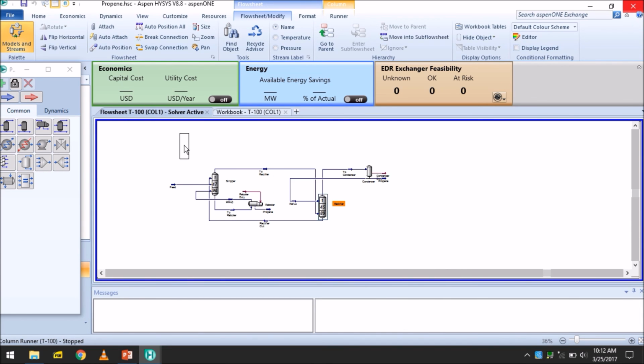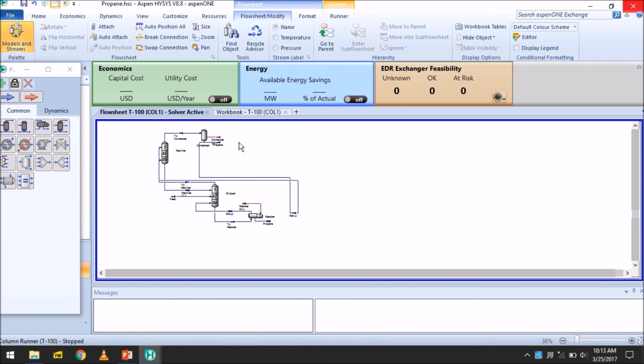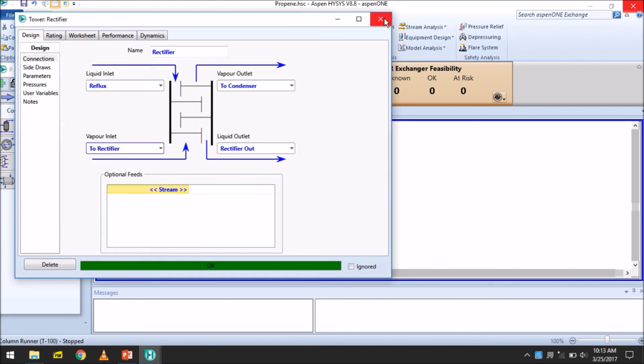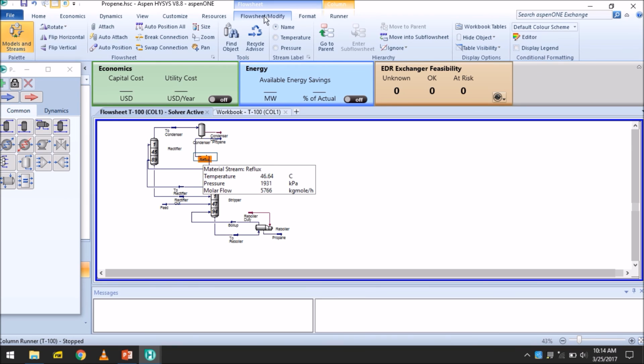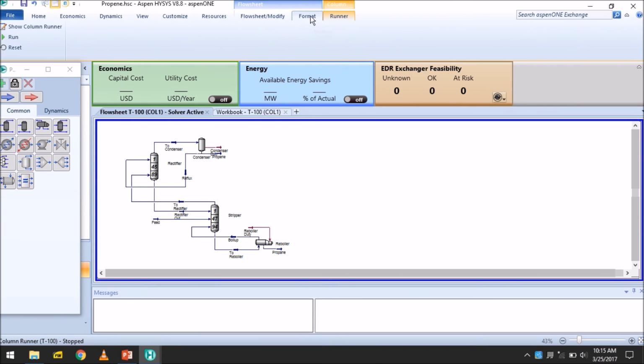Now you should reorganize your PFD so that the reboiler stage comes below the condenser tray section, which, if you have any knowledge of distillation columns, is the right way to do any sort of distillation. So make sure you reorganize your PFD so it is better understandable. It will not affect the results, but a disorganized PFD will be a bit difficult to understand. So reorganize it.